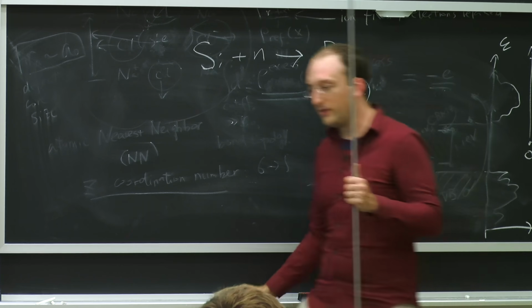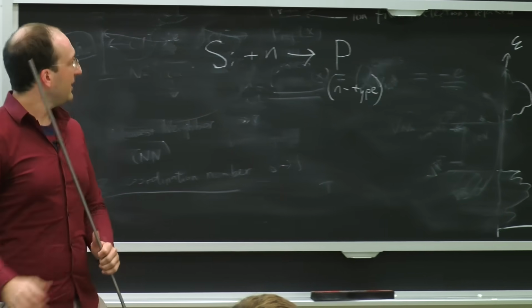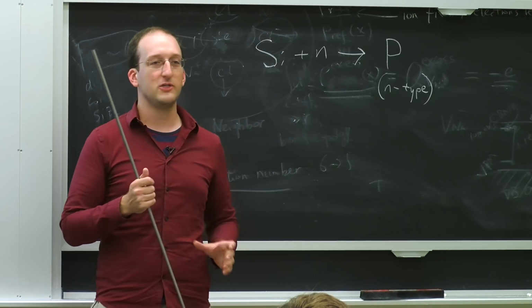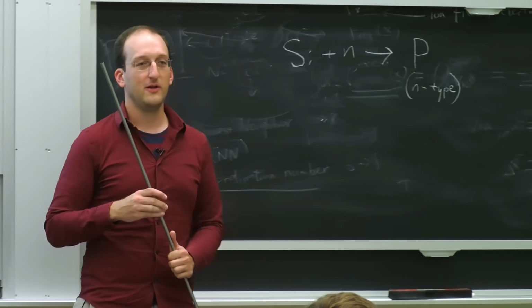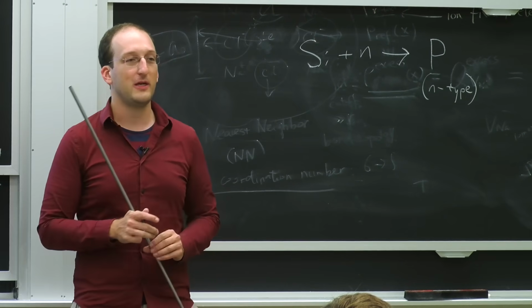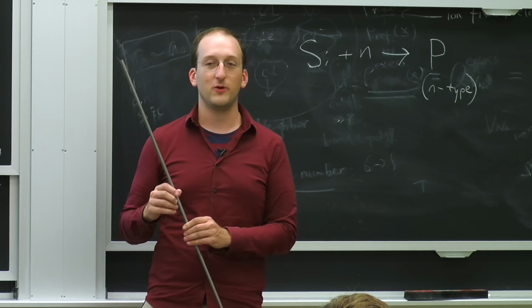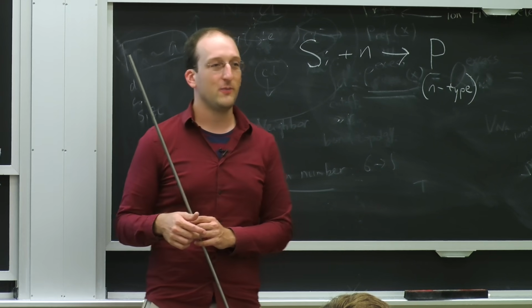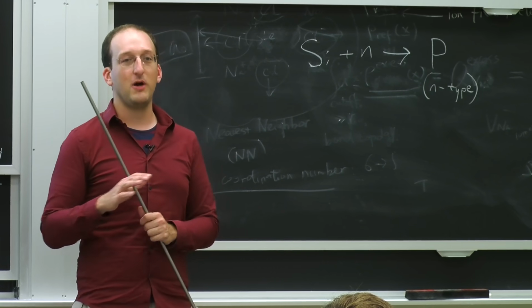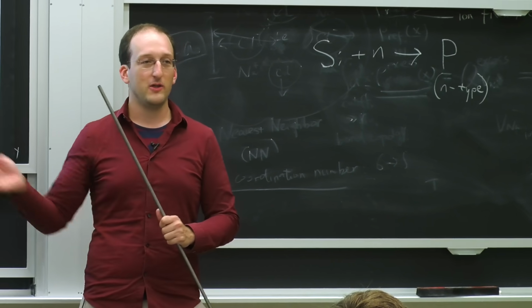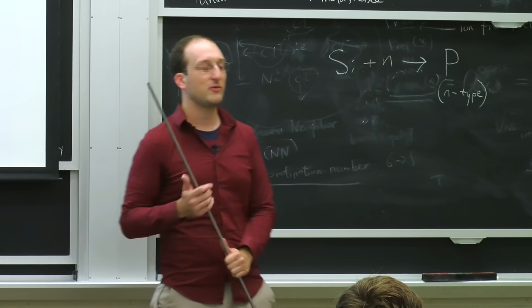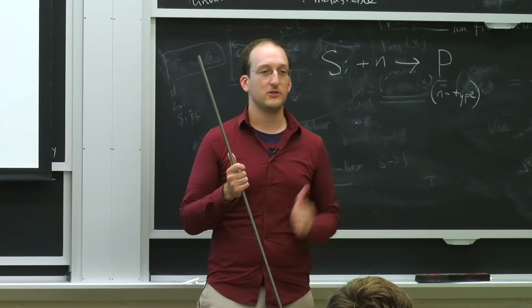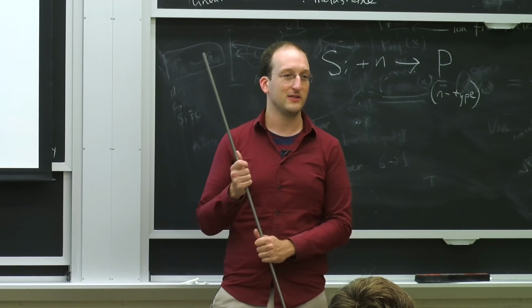It's a sort of extra negative charge type dopant that changes the conductivity of the semiconductor. There's lots of different ways of doping semiconductors. One of the best and most uniform is to stick things in the reactor. So back when silicon ingots were smaller, like 4 or 6 inches in diameter, there was a constant train of these things traveling through the reactor, getting irradiated and being sold and then cut up into wafers to make devices.